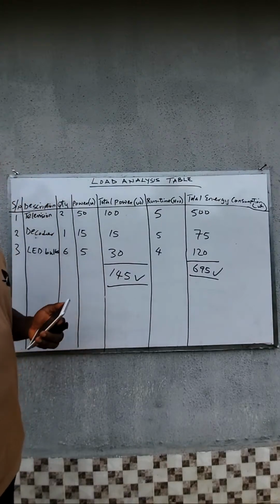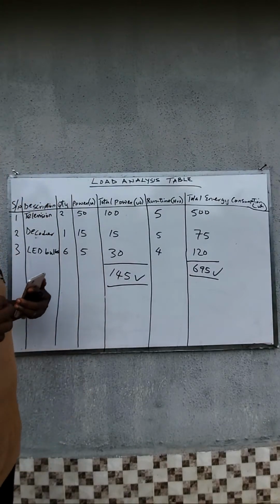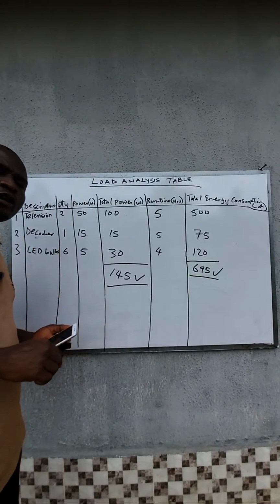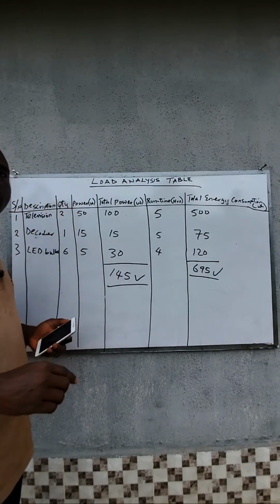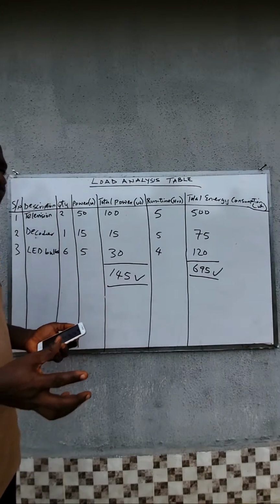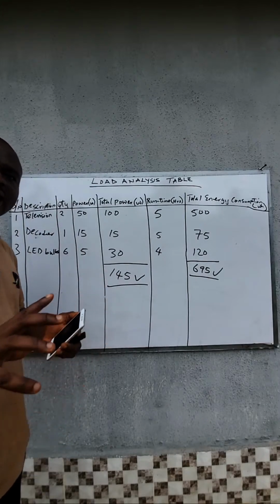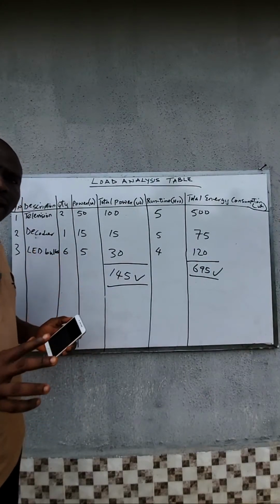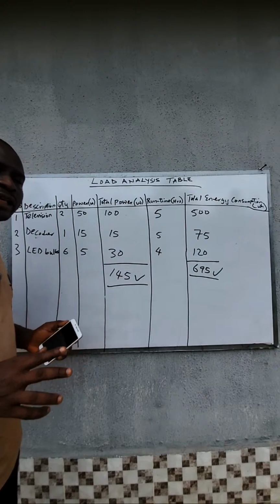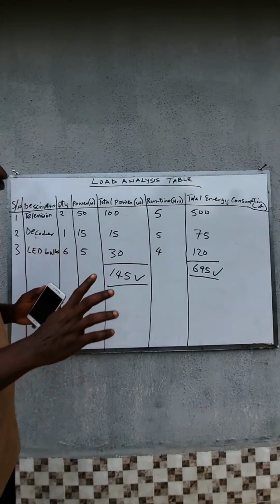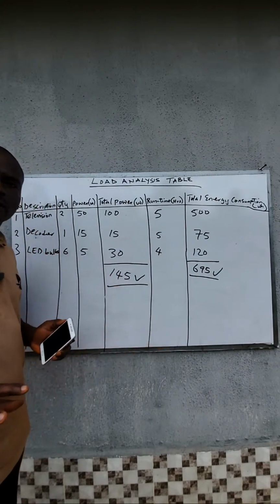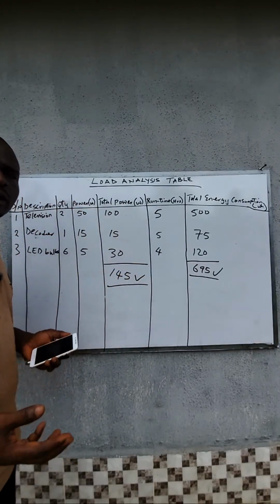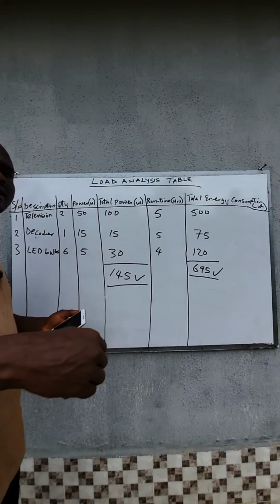Now, we also have inverters that are hybrid. They have inbuilt charge controllers, and they can also use power from the grid or the generator to charge the batteries. These solar battery chargers are designed in such a way that they will properly charge the battery bank, in a very good way that it will not destroy the battery. And they have about 3 steps of charging: absorption, float charge, bulk charge, and we also have equalization charge.